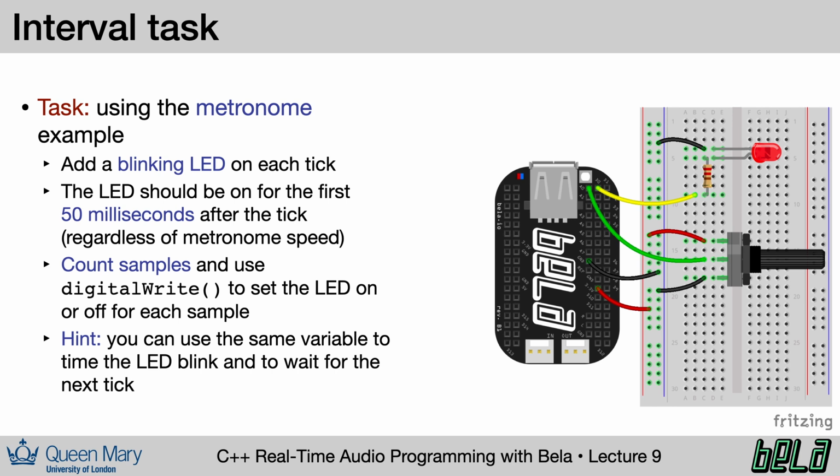Here again is the circuit for the Bela Mini. If you haven't yet put the LED onto your breadboard, do that now, remembering that the short lead of the LED should go towards ground. Pause the video here and try this.